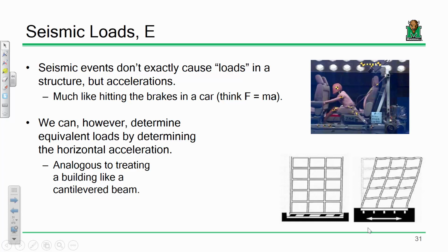So our philosophy changes a bit, and the way that we design structures changes a bit. When an earthquake hits a building, there's no earthquake monster pushing on the building. You're not putting a load on the building. You're taking the building and pushing it through an acceleration. So it's like being in your friend's car, your friend's driving, they hit the brakes, and you fling forward because there's a sudden change in acceleration.